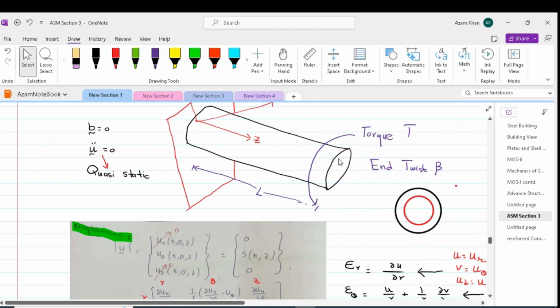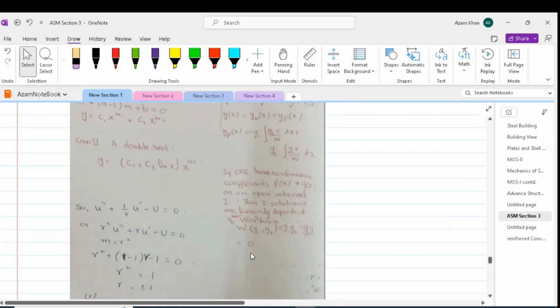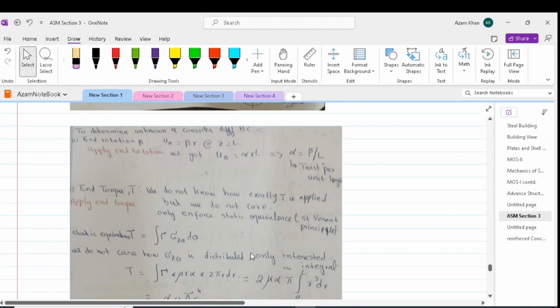Thus, we can have a clamp applying torque at the surface, or we can have a small portion of the cross section with a torque applied at a point. If we are applying torque, we will have a region of disturbance or stress concentration at the point of application.